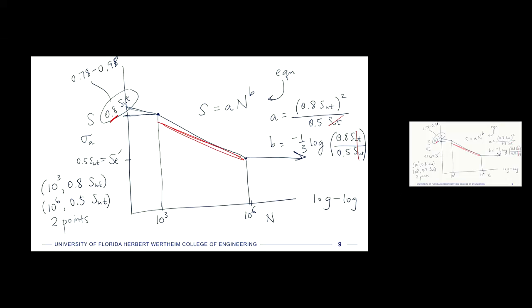So then the general procedure is if you don't have the SN curves, but you know the ultimate tensile strength, you sort of create a fatigue curve like this. And then once you calculate what your SE is, you want to know sort of where you are on this curve. Sorry, let me say that a little bit more clearly. Now you have this curve, and you want to modify it for the specific situation the component is in, right?